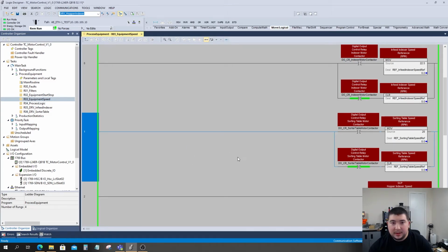Alright, so now that we have determined our optimal operation speed, the next thing we want to do is be able to regulate this speed in a way that we can actually control our acceleration and deceleration. So the idea here is we could technically have the drive give us a ramp rate on its own. If you remember, there's a potentiometer on there that allows us to control the acceleration rate. And we could just leave it there.